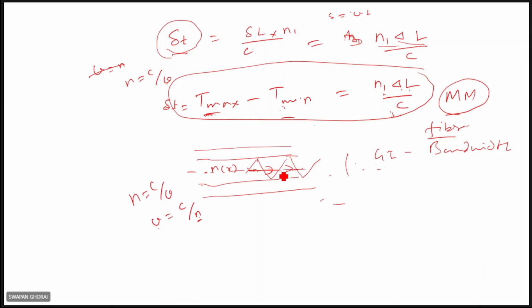Also, we'll see that when you use coherent sources, some coherent noises are also there. Suppose in between the fiber you have some splices and connectors. If you use connectors or splices in the case of single mode fiber, then some noises will be taken into account. That is because of coherent noise, speckle noise, etc. So when you consider the sources, that time it will be clear.